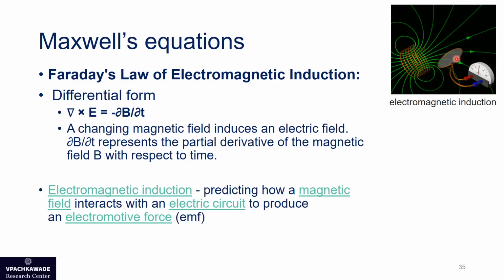So some of these magnetic lines, or an effective magnetic flux, are passing through the wire loop. Because of that, this effect will induce charge carriers flowing through this wire, which is in the form of a loop. Or in other words, a current will start flowing in this wire. If we cut this wire, we can have an open circuit and connect a voltmeter across it and measure the voltage. So this is the principle of electromagnetic induction.